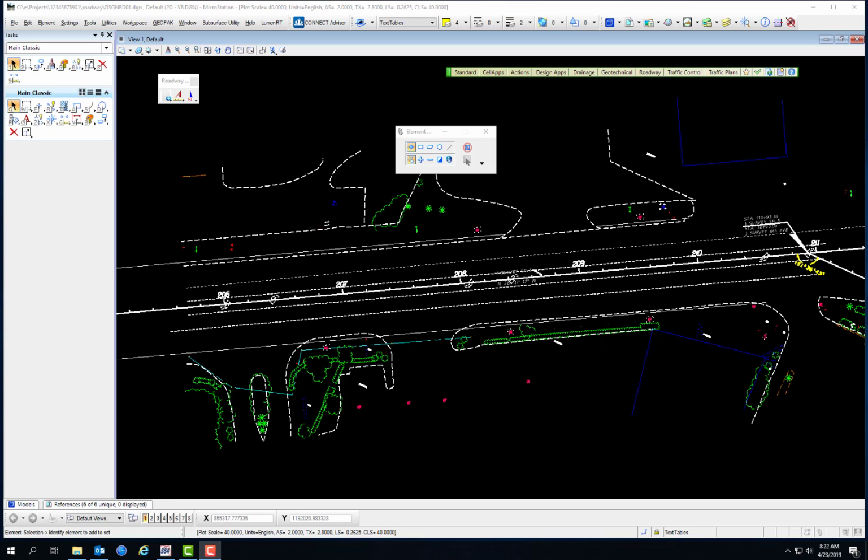As the drawing becomes more and more complex, it may be useful to open multiple view windows. MicroStation can have as many as 8 drawing view windows open at one time. Opening multiple view windows allows users to focus on details as well as an overview of the design without getting lost in between. The view currently being worked on is known as the active view and is indicated by a highlighted title bar.